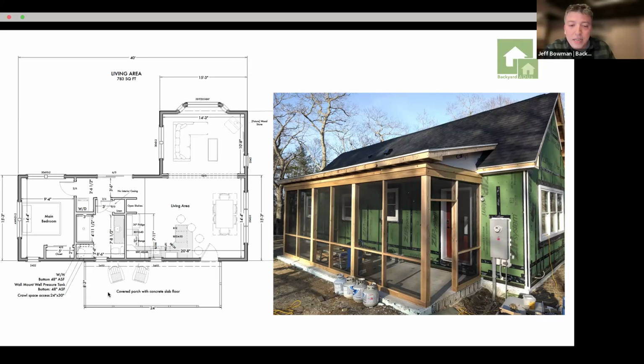So yes, you can have a generator switch in your electrical panel where you can essentially choose which breakers you want to turn on with the generator, switch off the main power coming in from the street, and then plug in your generator and have all of that run off your generator. And a lot of homeowners on the Cape are thinking about it too, because of the frequency of power outages. So it is possible.